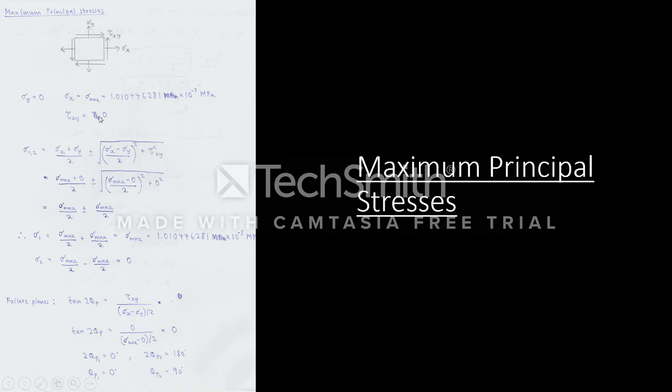Thereafter, I found the maximum principal stresses, which are sigma 1 and sigma 2. Sigma 1, as it turns out, was equal to the maximum bending stress, and sigma 2 is 0. Also, I found the failure planes caused by these maximum principal stresses, which are 0 and 90 degrees.